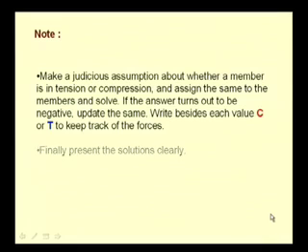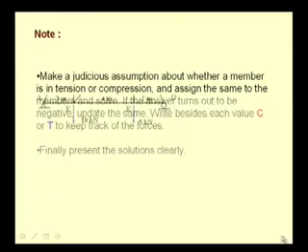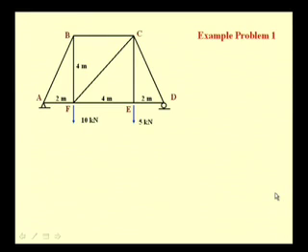That is, if we have originally assumed that the member is in tension and the answer turns out to be negative, then the member is in compression. Finally, we present all the determined forces along with the nature of the forces, that is either tensile or compressive. So, let us see the complete procedure with an example.